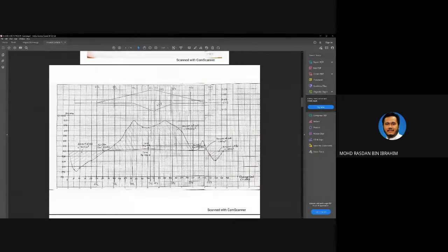If you do not want to cut off this hill over here, your road must go up and then go down. So why did she have her design like this instead of going up? It is because of the gradient of the road. You need to measure the gradient, the slope of this line and the slope of this line. Where's the calculation here?